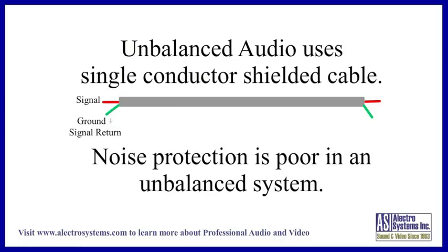The noise protection provided by an unbalanced system is quite minimal. It is only marginally safe to run a distance up to 15 or 20 feet, especially with low-level signals such as a microphone or electric guitar.